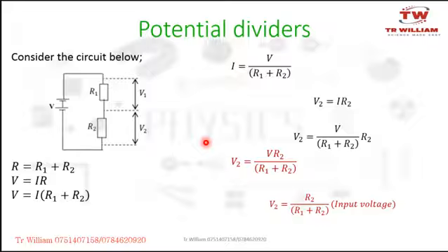How about we use a transformer to reduce the voltage if it is big? Now remember, will you keep putting a transformer everywhere because you want to reduce the voltage for every component? No. So that is why a potential divider becomes useful. But that is smart of you to think like that as well.